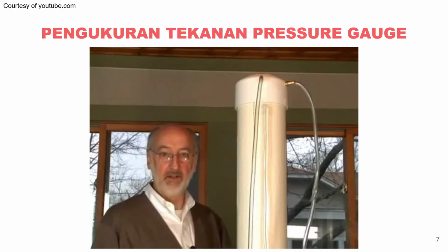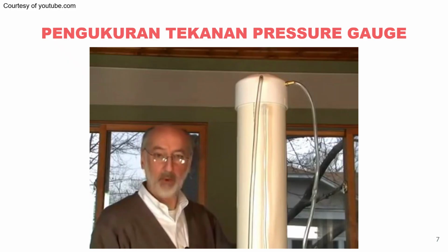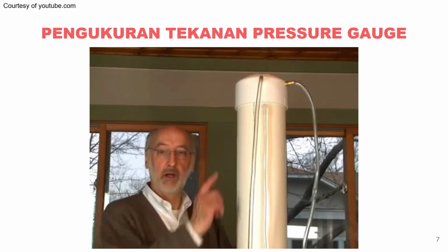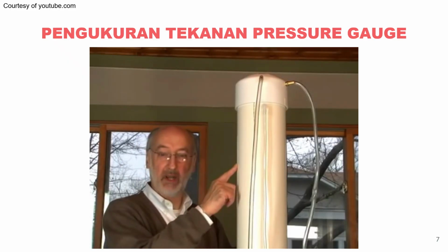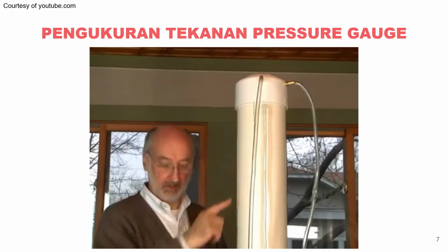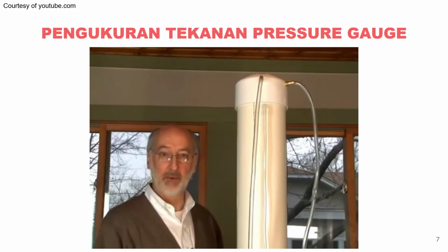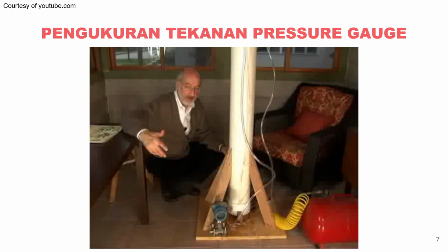Now that we're taking a differential pressure reading, where we're reading the weight of the liquid compensated by any pressure inside the tank, we can still get a true reading just as we did when the tank was vented. This is a very simple but very useful method for measuring tank level. It only works with liquids.